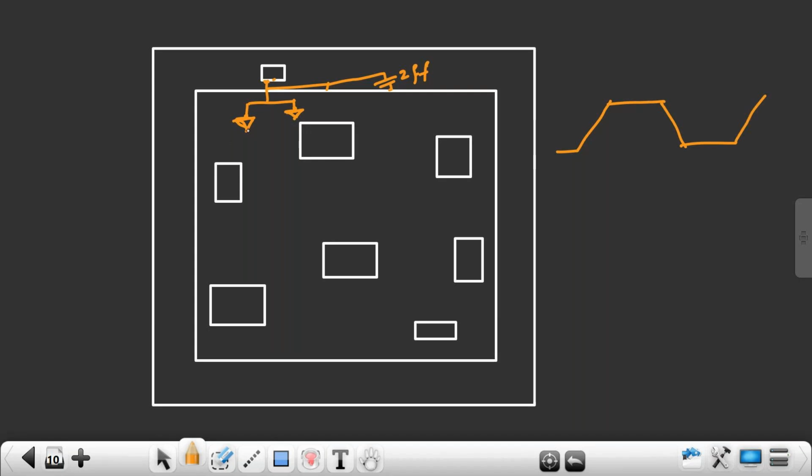And this buffer will connect to this flip-flop. It will connect to this flip-flop. Again, I cannot connect from here to this flip-flop because the length increases. Length increasing means the capacitance starts increasing. If the net length increases, capacitance increases. I cannot have a bigger length.